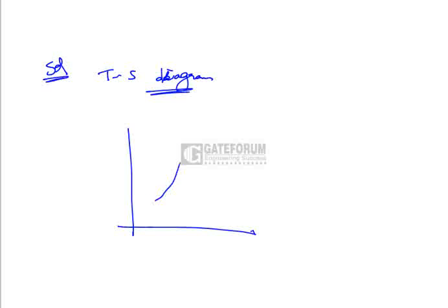First draw the TS diagram for the given VCR. Here the condition is that the vapor is just dry at the end of compression. So at the end of compression the vapor is dry, that is, let us say 1 to 2, and 2 is on the saturated vapor line, and 2 to 3 is condensation, and 3 to 4 is expansion, and 4 to 1 is evaporation. So this is the TS diagram for the given problem.